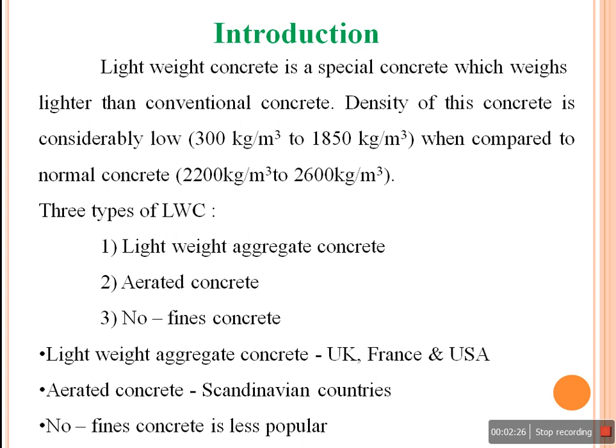If we are omitting the sand fraction from the aggregates and manufacturing concrete, you call it no fines concrete. Generally lightweight aggregate concrete is popular in UK, France and USA, aerated concrete is popular amongst Scandinavian countries, and no fines concrete is very much less popular.